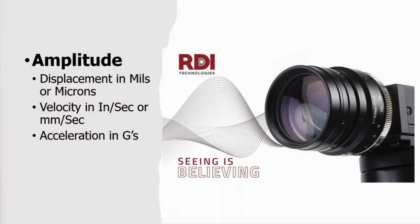And often it's just a preference of the vibration analyst, whether he or she uses displacement, velocity, or acceleration. And another thing to know about these amplitude units is that they're all mathematically related to each other. So you could measure the displacement and then mathematically calculate the velocity, or you can measure the velocity and mathematically calculate the acceleration. Remember that for motion amplification, we are measuring the displacement, but we can mathematically calculate the velocity or the acceleration from the displacement measurements.